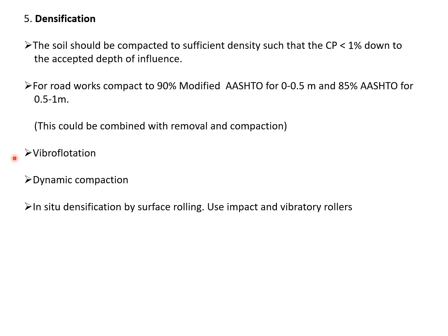Vibroflotation, dynamic compaction, in situ densification by surface rolling. Use impact and vibratory rollers for more effectiveness. So that's all about the collapsible soil.